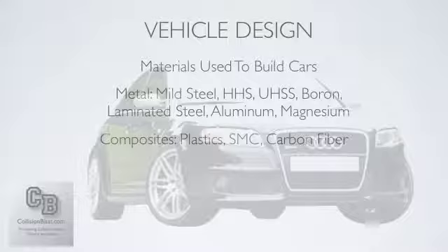And then they also started developing ultra high strength steels and borons, and this is even harder steel. This is done with alloys and different types of heat treatments, making this metal really hard. Of course, this is your real strong steel, and they're going to use it around the passenger compartment, inside of the doors, in the intrusion beams and areas like that, to keep the passengers safe.